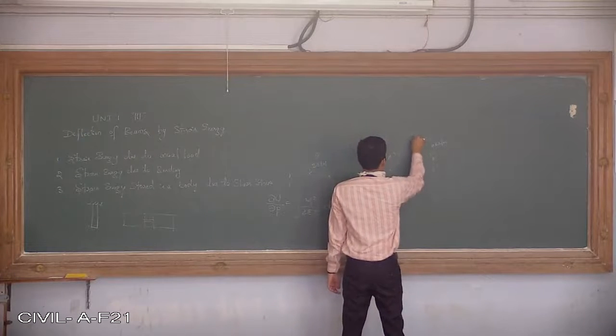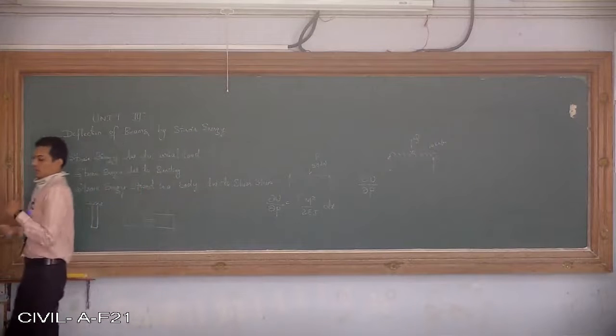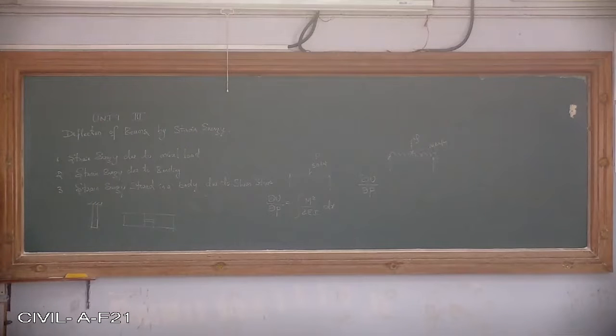The importance of taking Q is that it acts as the imaginary load, with respect to which we differentiate. When you have dou M by dou Q, at last you replace Q equal to 0, and put whatever load remains in the variable P.